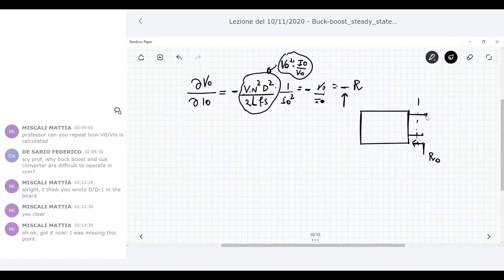The operation you can do is to switch off all the independent sources in the circuit and apply a specific test voltage or current, for example a voltage test source VT.